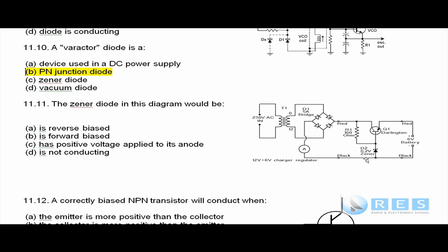What the Zener diode does for us is produce a constant voltage here depending on its breakdown level, in this case 8.2 volts. So we would get a constant 8.2 volts. So a Zener diode is a voltage regulator. And to answer the question at last, the Zener diode in this diagram would always be reverse biased. So your questions are not so much about applications, just a basic knowledge of whether they're forward or reverse biased and how much voltage is necessary to make them work.